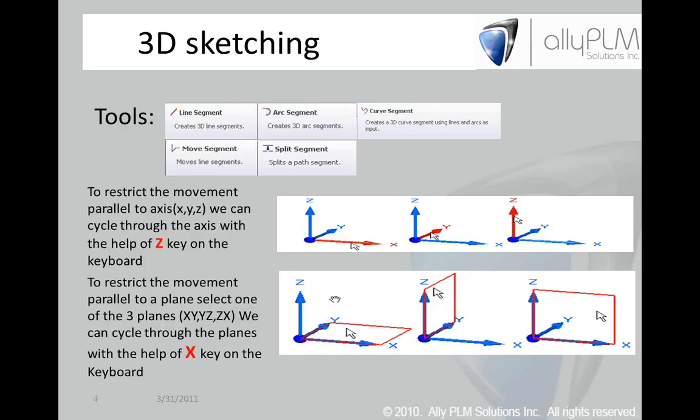The first thing we'll cover is 3D sketching. Inside the framing environment, there's a group called segment group, and it gives you flexibility to choose different axes in order to create your 3D sketches. You can also define multiple planes inside your sketch. Usually, in assembly sketches or part environment sketches, we select a reference plane and our sketch is tied to that reference plane, so it's a 2D sketch. But here it gives you more flexibility in terms of defining the direction and the plane.